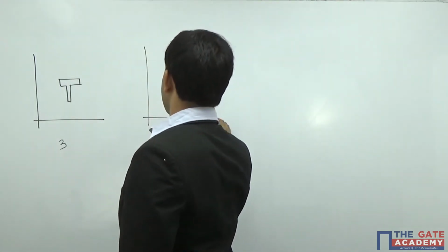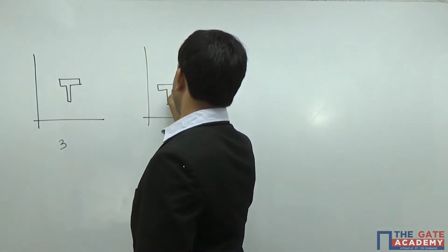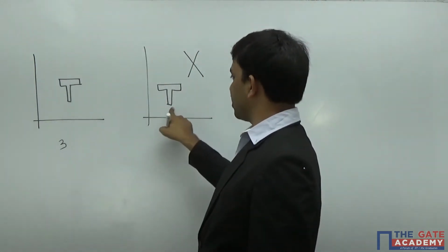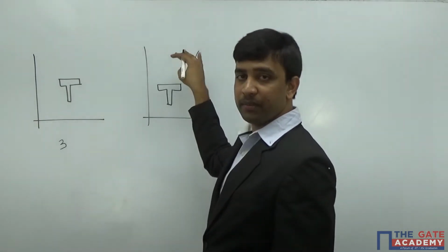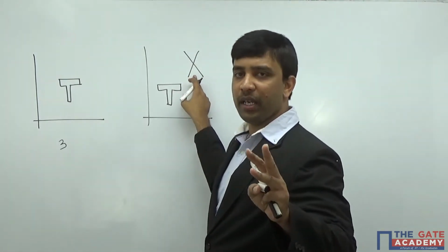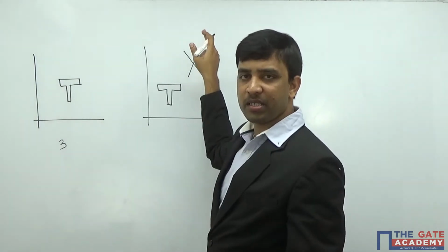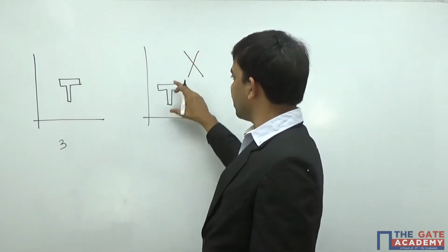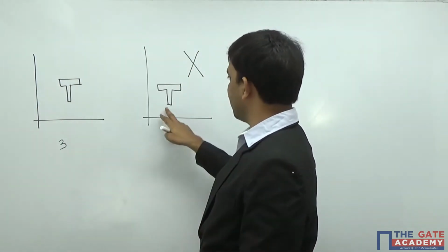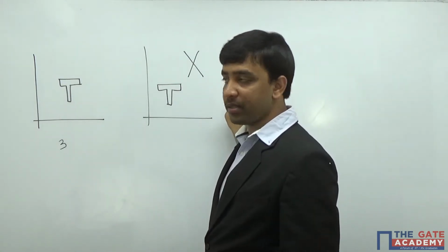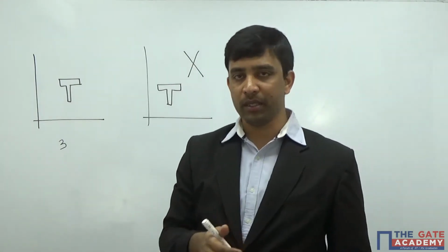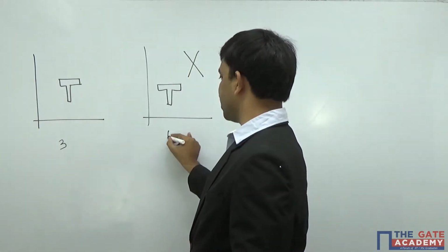So if I say the system has 2 elements like this, number of elements are 2 in the system. So this is my system. If you look at the system, I can move this t in x direction, I can move t in y direction, I can rotate t. So these are 3 degrees of freedom. Now if you look at x, without affecting the motion of t, I can move x in y direction, x in x direction, I can rotate this x. So I can say this t describes 3 degrees of freedom and this x describes 3 degrees of freedom. After some time, if this t goes to a new position, to describe that motion I need 3 parameters. If x goes to some new position, to describe position and motion of x, I need 3 more parameters. So I can say degrees of freedom for this system is 6.